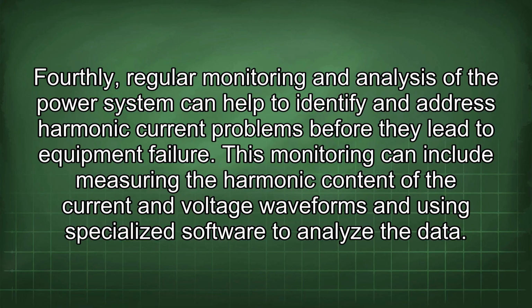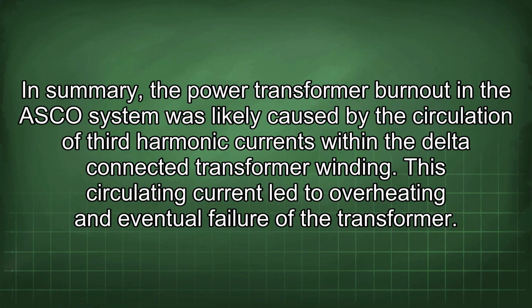the data. In summary, the power transformer burnout in the ASCO system was likely caused by the circulation of third harmonic currents within the delta-connected transformer winding. This circulating current led to overheating and eventual failure of the transformer.